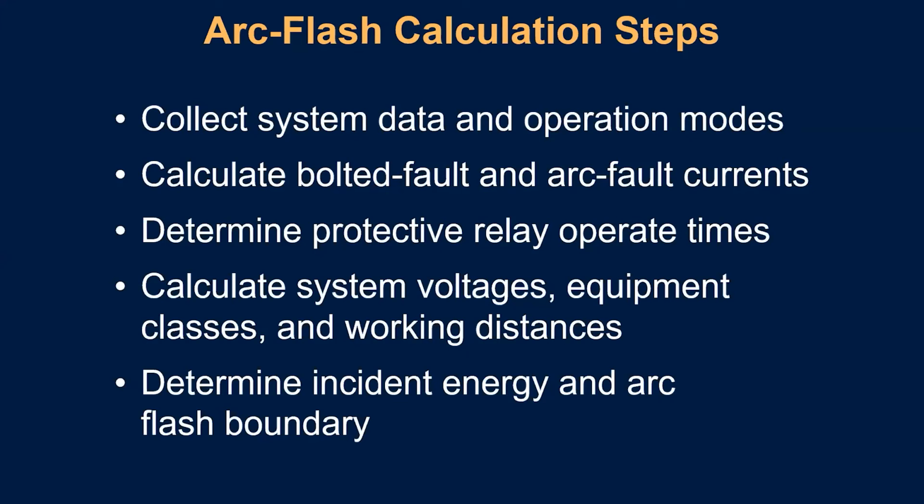System voltage, equipment classes, and distances. All these things come into play when it comes to calculating arc flash energies. And the IEEE 1584 and NFPA guides provide some common working distances that you can base it off of as well. All these put together will give you the incident energy and also the arc flash boundary that you can estimate.